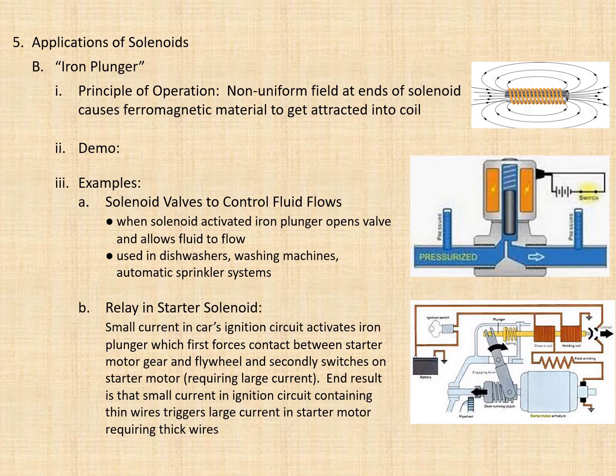The gear on the starter motor is then not able to get into the correct position on the flywheel, and you hear a rapid clicking sound as it's not allowed to fully engage the flywheel.